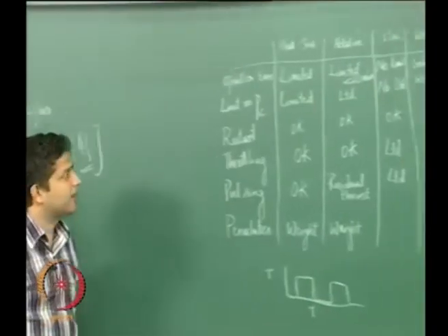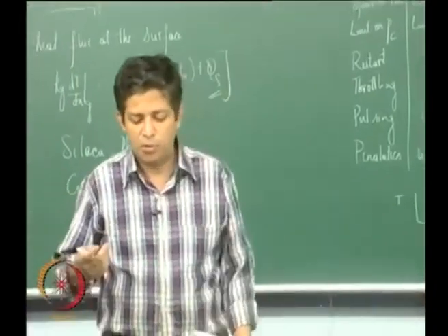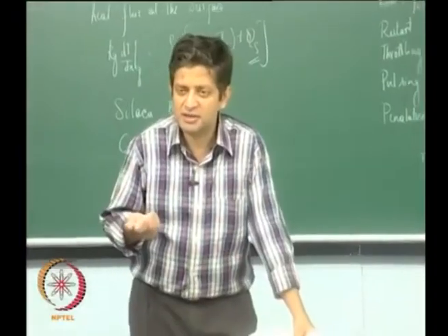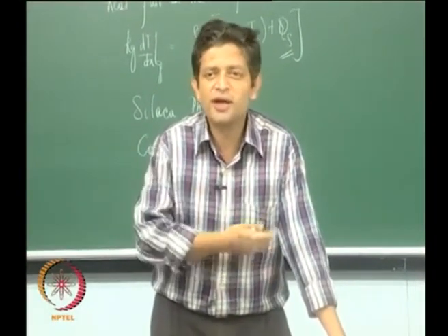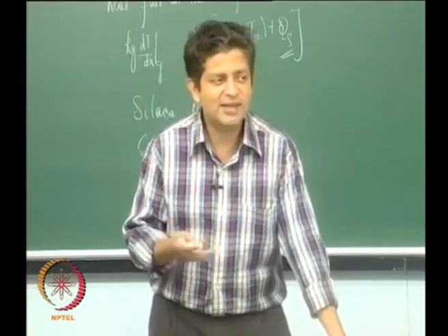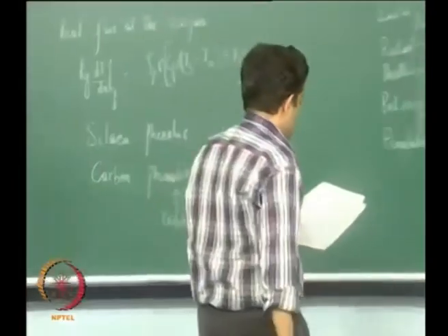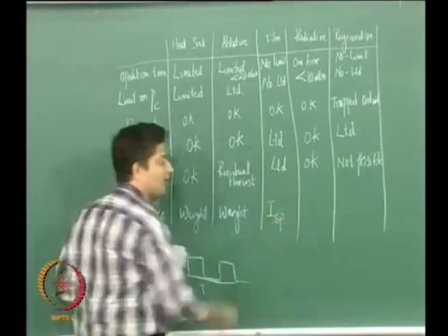penalty. And in film cooling, if you remember, we are using one of the fluids, that is fuel on board, and this is not contributing a great deal towards ISP, right. So in a sense the penalty here is ISP.